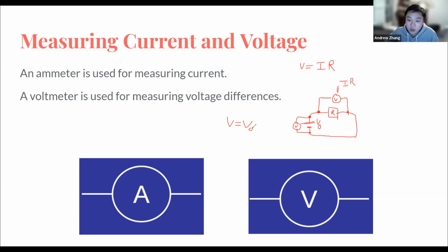And you might notice here that both of these points basically correspond because they are both connected by a wire and just a wire, which means that if you measure the voltage difference between them, as we showed before, the voltage difference is 0. So similarly, we could say the voltage difference between here and here is 0. So we can basically combine these 2 points. I'll just do something like this. We could instead measure the voltage difference from here and here, right?